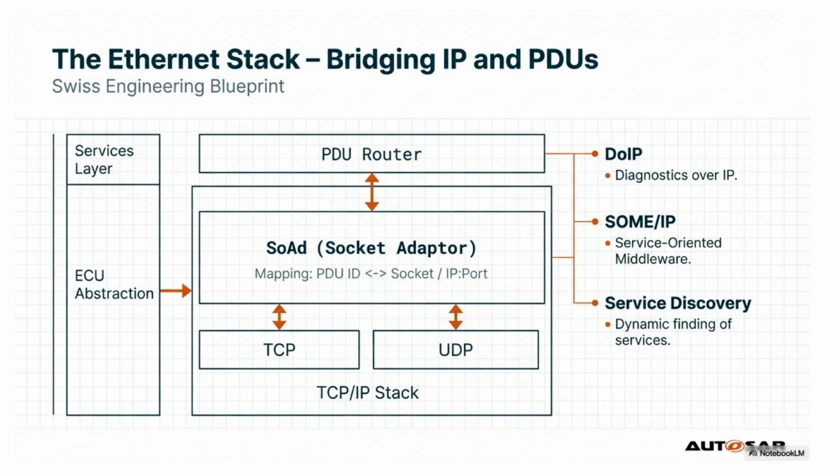As automotive architectures evolve, the Ethernet stack has become vital for high-bandwidth applications like ADAS and infotainment. In this stack, the PDU router interacts with the socket adapter (SoAd), which is responsible for mapping traditional AUTOSAR PDUs to specific TCP/UDP sockets and IP ports.